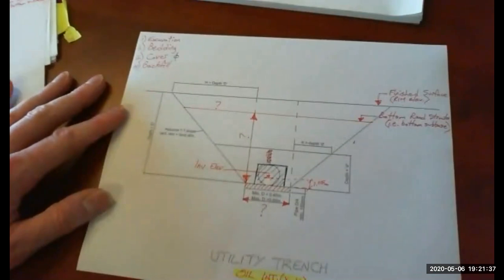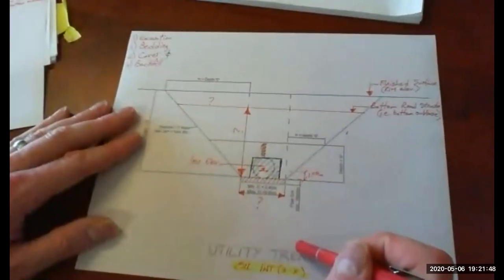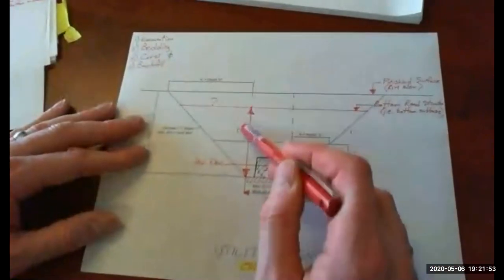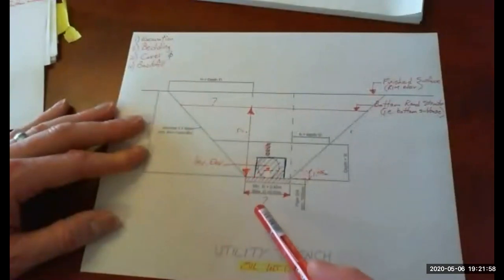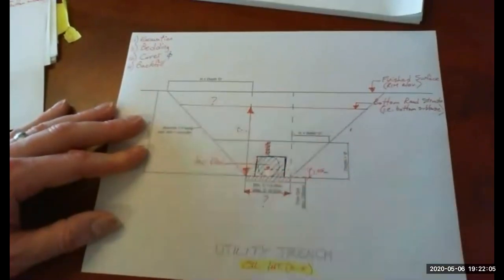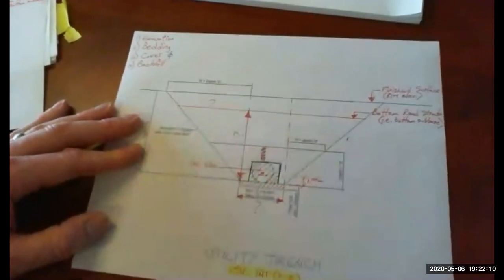Now it's not square, it's a rectangle, right? The width is less than the length. So you're doing the same types of calculations for the Oil Interceptor as we did previously with the pipe. So you're calculating depth to bottom of interceptor. You calculate the bedding layer, the 100 millimeter thick layer. You're calculating one-to-one slopes up. You're doing similar widths for your triangles.